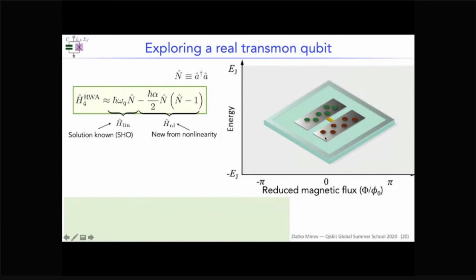And so what does this physically begin to look like? Well, let's look at some experimental parameters. So here's a device that I designed and measured some time ago, and it has the following real parameters. The capacitance between this pad and this pad, which maybe we can write like this, is very small. It's 65 femtofarads. It's a pretty small number, but very typical for these kinds of devices.